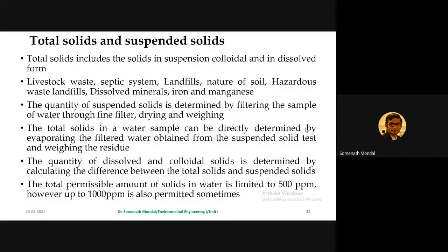So by weighing, we can determine the inorganic solids, and deducting it from the total solids, we can calculate the organic solids. There are several ways by which we can get the values of total solids and suspended solids. Once the inorganic part is known from the muffle furnace test, we can directly get the organic part by subtracting it from the total solids.